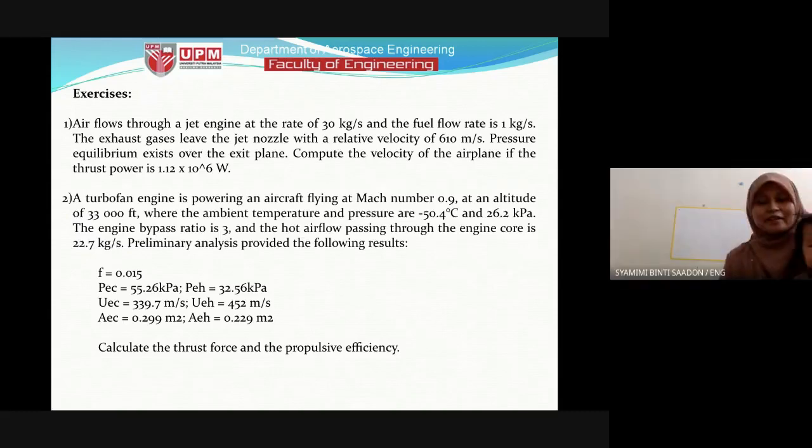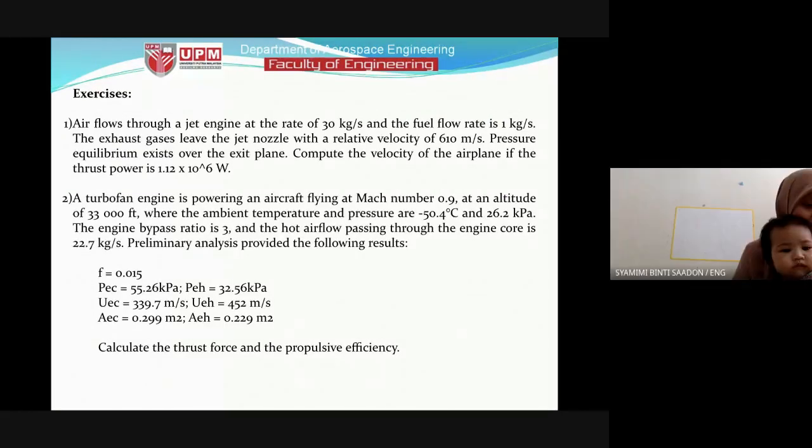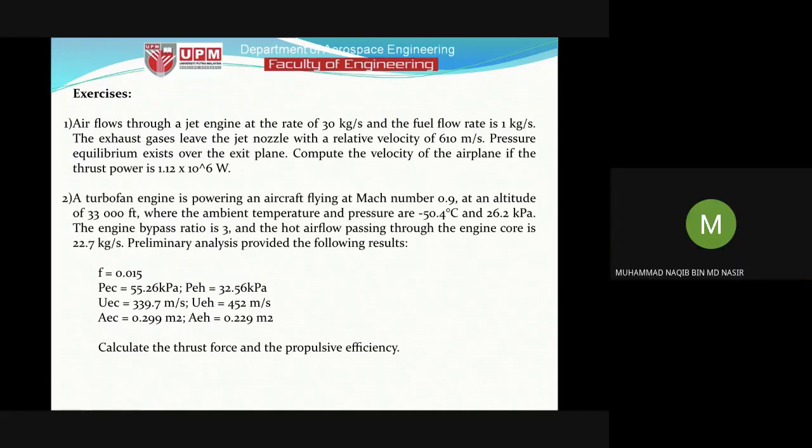Doctor, the temperature, do we need to change to Kelvin? I think not, right? For U? Yes, you have to, because R is in terms of 287 joule per kilogram per Kelvin. Okay, Doctor, thank you.